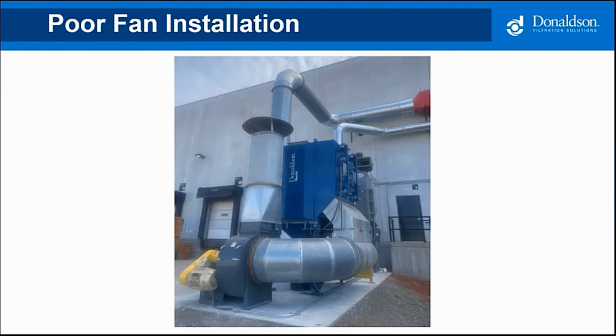And then on top of that, they put a rain cap on top. The rain cap will prevent rain from getting in, but there are drain holes, where the plug can be removed and left open, so that if rain or snow gets in, it will work its way out. But this is causing a back pressure. So once again, I needed 9,000 at 12 inches of static, and you're adding this resistance, and my resistance demand is now greater than 12. I hope it doesn't exceed 13, because that's all my blower will have.